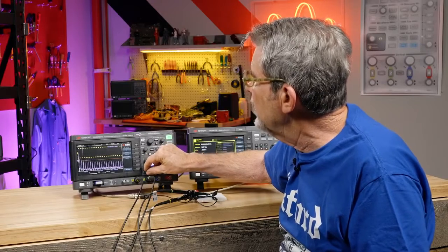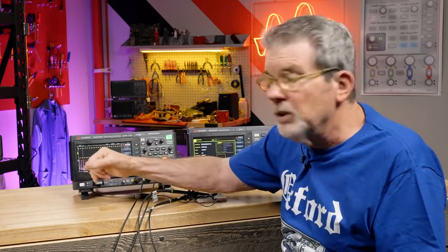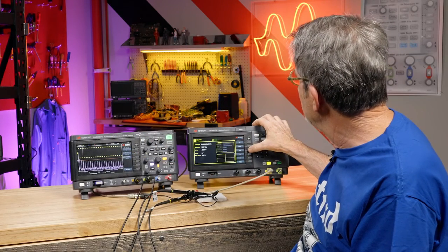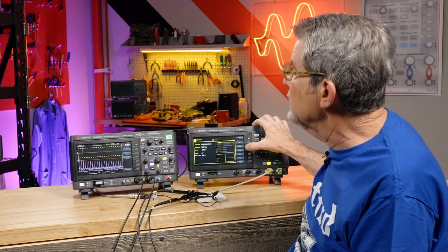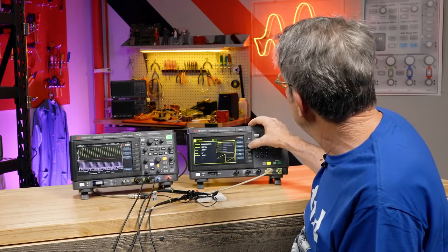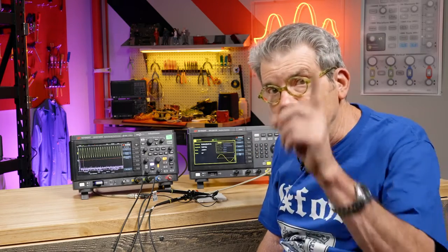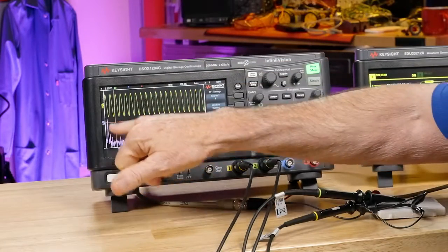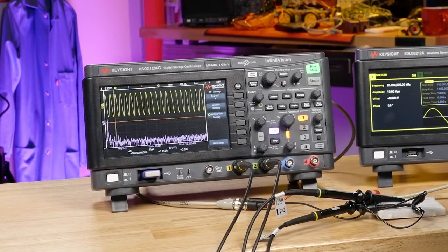And what about other wave shapes? So this is what a square wave looks like, the fundamental and all the odd harmonics. What if we selected a triangular wave? Now you get odd and even harmonics. What if we selected a sine wave? Theoretically, we should get one peak only, and that's the frequency, that's that peak there at 20 kilohertz.